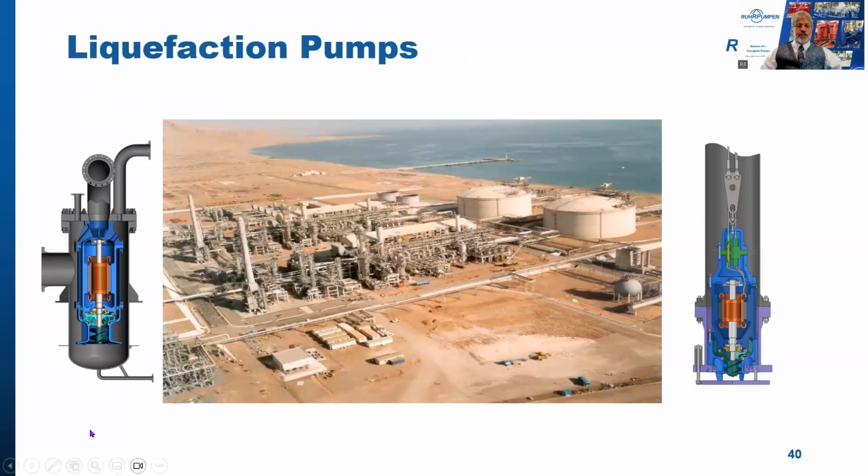Let's look at the whole LNG cycle. This is an LNG liquefaction plant. The main LNG shipping pumps are high flow, low head pumps, transferring the LNG to the atmospheric storage tanks. The in-tank pumps, here on the right, export the LNG to cargo tankers at these jetties.